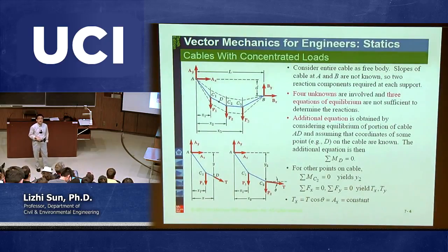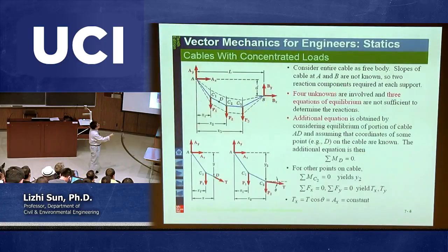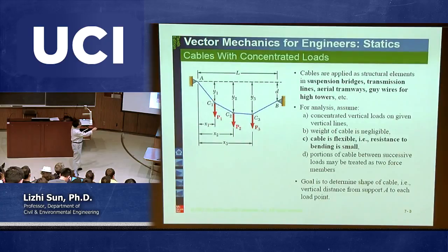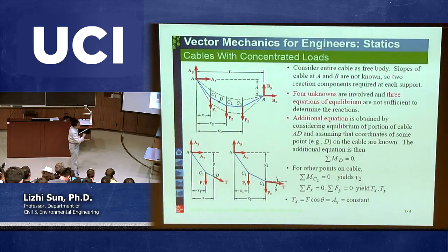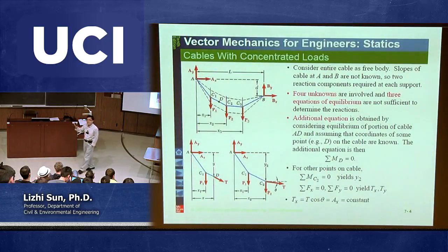called AX and AY, which are unknowns. We know that. Then we cut point B, which is another pin, and we gave another two reactions. Assuming we know these forces, let's just put those forces here. This is what we call the free body diagram for the entire structure. The question is, for any given two-dimensional problem, you have to agree that's two-dimensional, right? How many equations are we supposed to generate? We can generate 3.